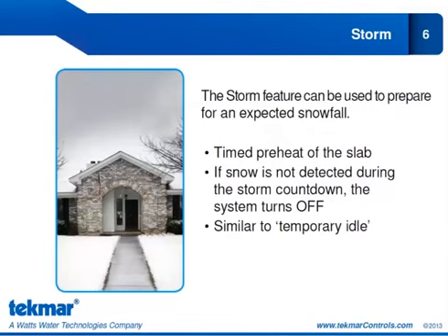Storm, as I mentioned, is a new feature for TechMar. It is similar to temporary idle if you are familiar with the temporary idle function in our earlier controls. Storm is a timed preheat of the slab. So if you hear on the weather report that we are expecting a snowfall sometime today, what you might want to do is to preheat your slab. So instead of starting from a cold start, we can bring that slab up to a certain set point as entered by the user, and it can stay at that storm set point until it sees snow.